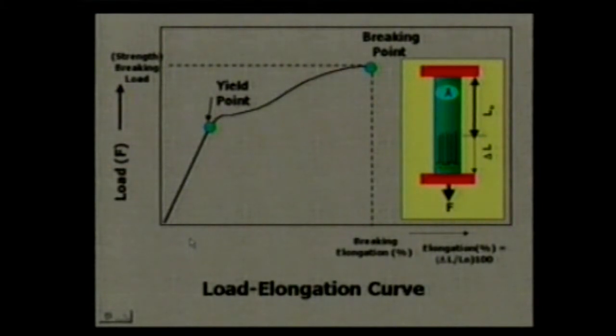And this point is extremely important, because which parameter should we care about? Is it really the breaking point or the yield point? Now, engineers designing any structure always base the design on the yield point.